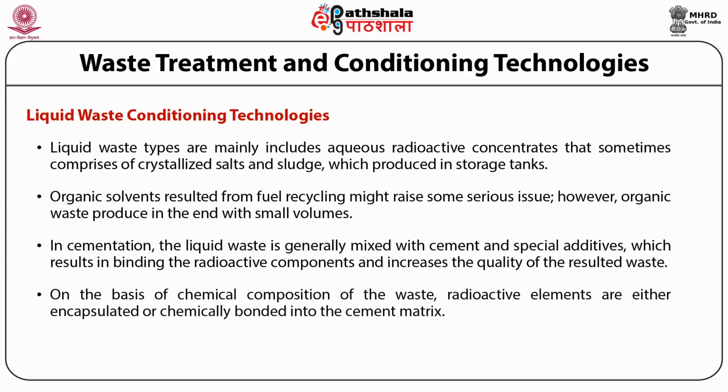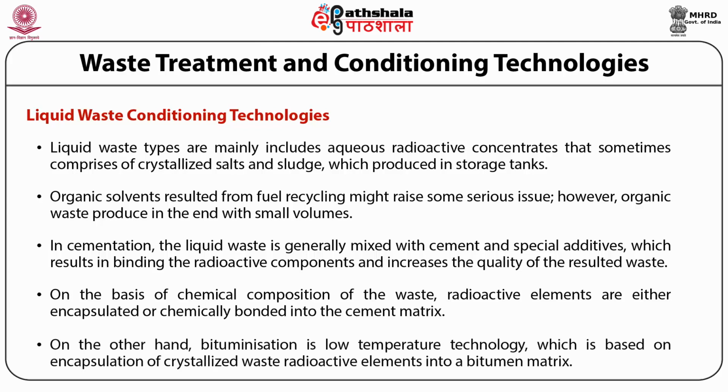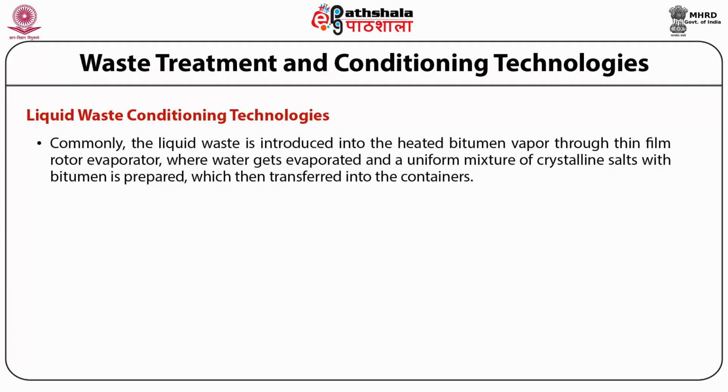On the basis of chemical composition of the waste, radioactive elements are either encapsulated or chemically bonded into the cement matrix. On the other hand, bituminization is a low temperature technology which is based on encapsulation of crystallized radioactive waste elements into a bitumen matrix. Commonly, the liquid waste is introduced into heated bitumen through a thin film rotor evaporator, where water gets evaporated and a uniform mixture of crystalline salts with bitumen is prepared, which is then transferred into the containers.